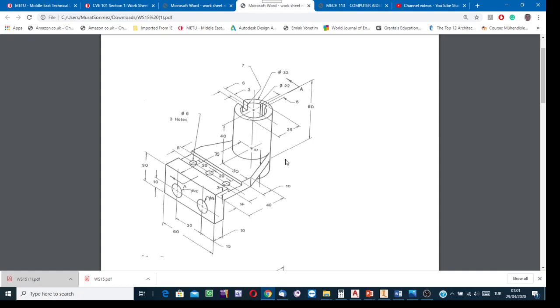And the other thing to check is the volume of the part to trim. If for setting the shape of the object, the part to trim by cutting the material is comparable or even greater than the volume of the object in its final shape, then in real life, in industry, the cutting process is certainly not recommended because it requires more energy and more time.